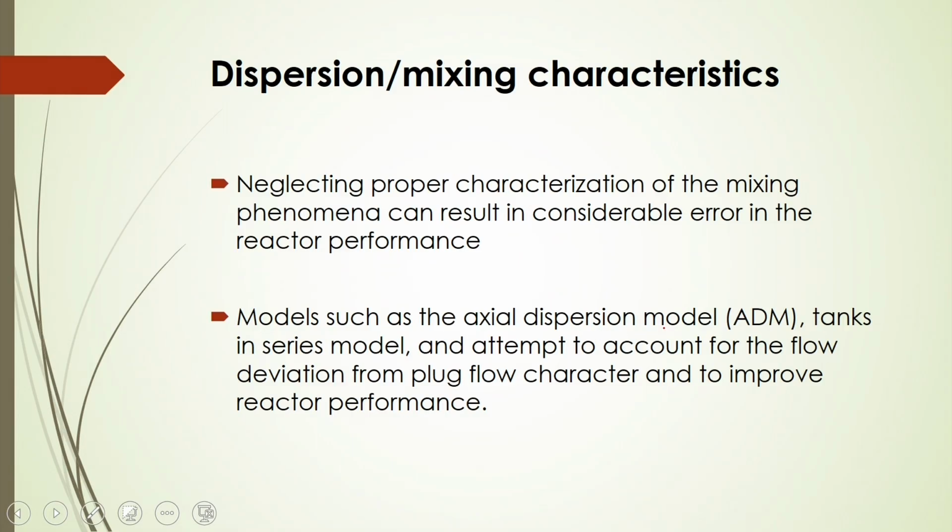Another important factor in characterizing the monolithic reactor based on hydrodynamics is the mixing characteristics. Neglecting the proper characterization of the mixing phenomena can result in considerable error in the reactor performance. In that case, models such as the axial dispersion model and the tanks in series model attempt to account for the flow deviation from plug flow characteristics, and to improve reactor performance, you have to analyze the mixing characteristics based on that model.